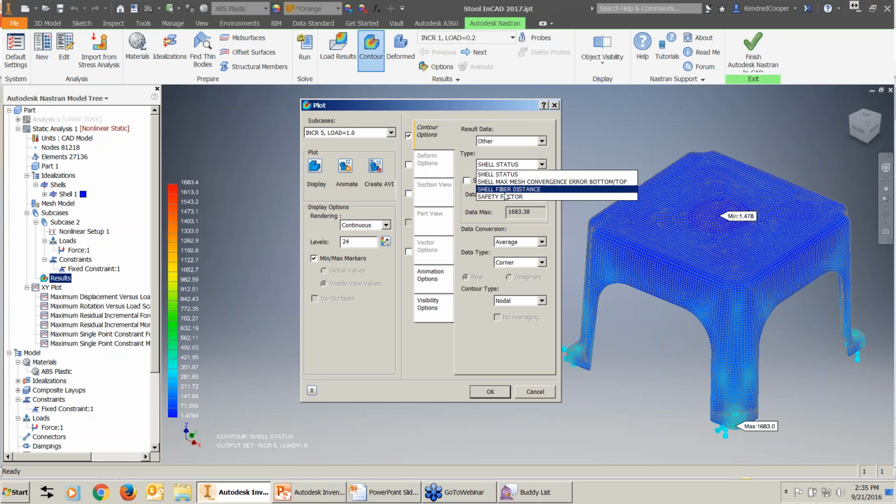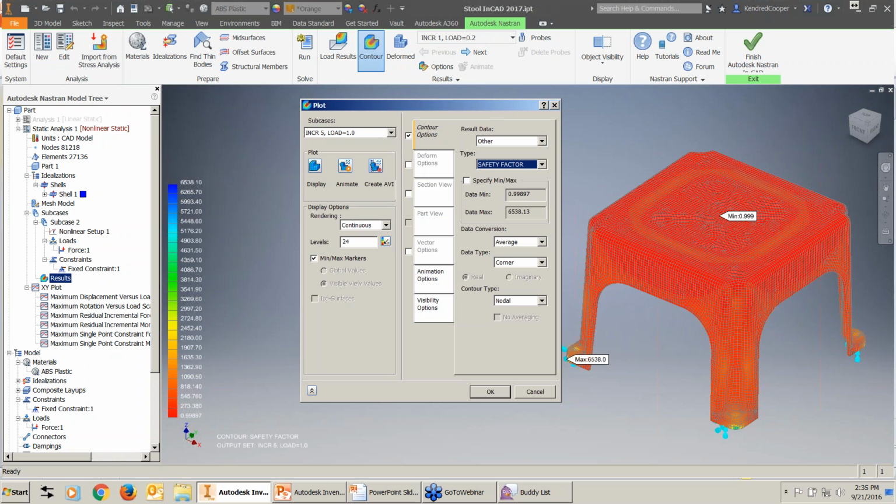Lastly, let's look at our safety factor. We were at 0.57 and 0.6 respectively for Pro and Nastran running a linear. Now we run it as a nonlinear and we see we're right at safety factor of 1, almost. So as we put in the ribs, that's probably going to climb. I'd rather see a safety factor of approaching 10, 15, maybe even 20 if I can squeeze that out of the design. And the ribs are probably going to get that for me.